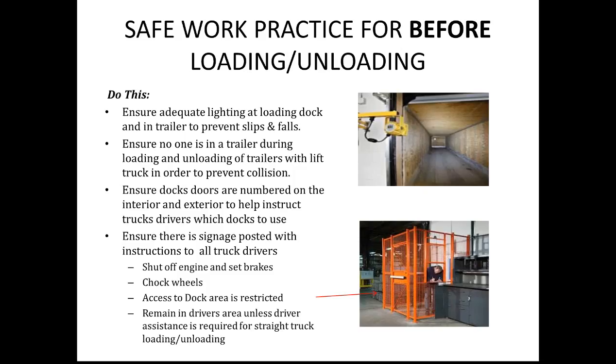The second thing is you want to make sure there's nobody inside the trailer during loading or unloading. And that may sound self-explanatory, but you'd be surprised how many people allow workers to either go in and inspect the load or to assist the forklift operator, for example, to restack pallets, or to help them position loads when they're being laid on the trailer. In my experience, that's where people get hurt. It's a confined area, so the rule is nobody should be inside that trailer while a forklift is loading or unloading.